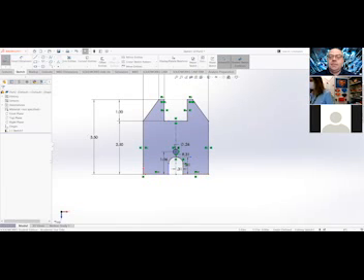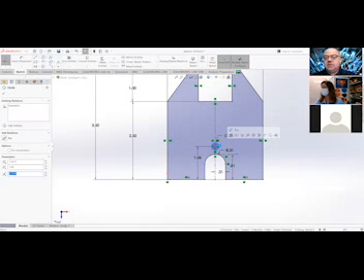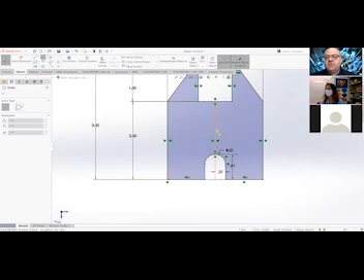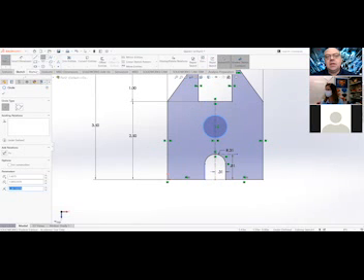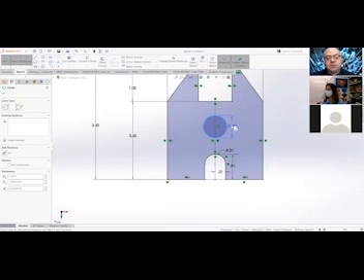Oh, top circle again? Okay, here we go. So I'm going to delete it out of this one because that's pretty quick and easy. So delete. So that's gone, okay? So what I did is I went to the circle, use the center point radius circle. Find the center line. It should highlight yellow. Just bring your pencil down. Just don't hit this yellow square. Just anywhere on that line. I'm going to do it way up here this time so that it looks more dramatic. Big old circle to start with. There's a circle. Then smart dimension. And then give the diameter first. So I select the edge of the circle.